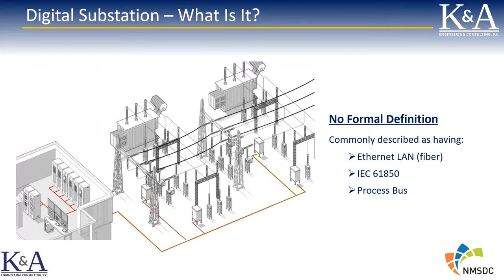Okay, so the first thing you'll find if you go out and try to look for a formal definition of IEC 61850 is that there really isn't one. In articles and papers and publications referring to digital substations, what you'll come across many times is that they'll say that if a substation is based on Ethernet local network communications and has IEC 61850, then it is a digital substation.